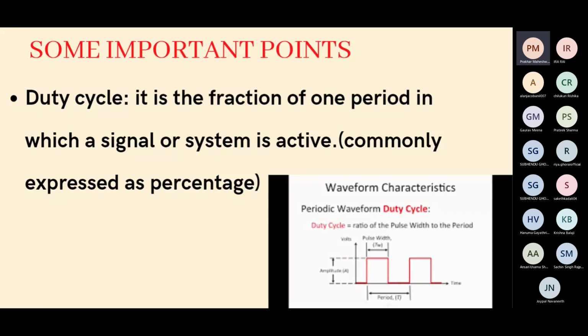Before we move ahead, there was some doubt regarding input pull-up. That we define in the pin mode. I think you have already seen this, the PWM and the input pull-up thing. How this happens is, we define a particular pin as input, and also we make it high by default. That's what we are doing when we define a pin as input pull-up.